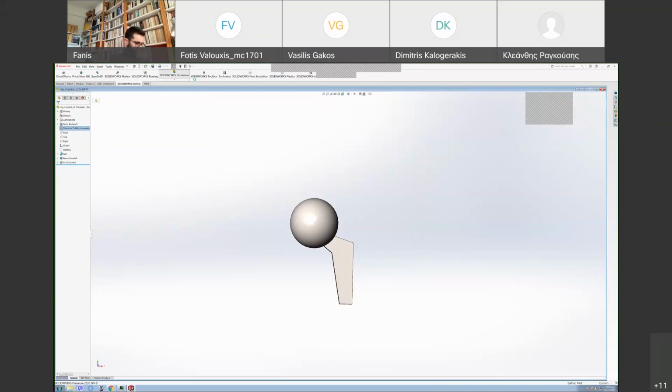Also, something to note, one reason we're not using the 3D models you created from the CT scan to perform finite element analysis is that usually because they have imperfections and the meshing is pretty complicated because there are many different surfaces, difficult model, and it takes a lot of time and a lot of processing power for these programs to analyze the stresses and the strains on such a model.